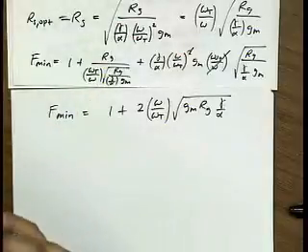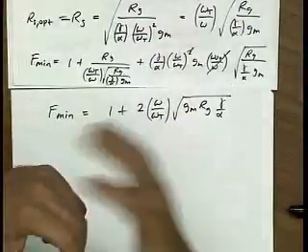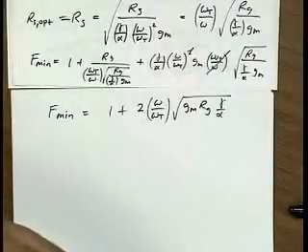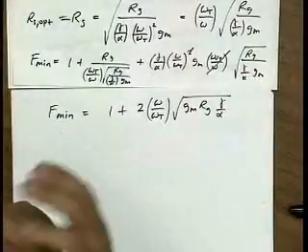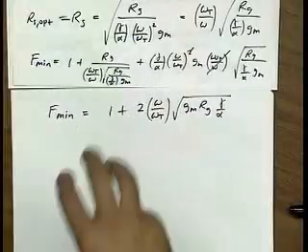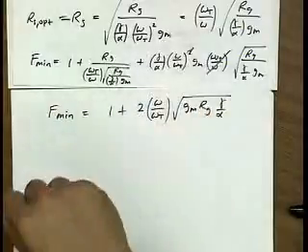Now in practice, of course, we can't live with an arbitrary source resistance. We usually are given a source resistance. It's like the antenna impedance or the filter that's driving our amplifier's impedance. But we can use impedance matching to transform it to some more optimal value. So here we're saying, what's the best source resistance to drive this amplifier? That would give us the minimum noise figure. Okay?